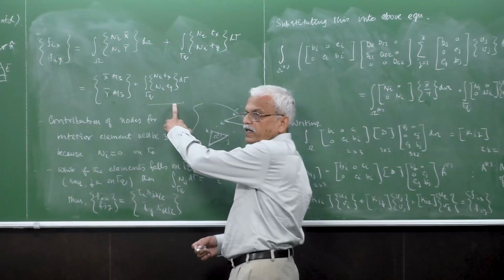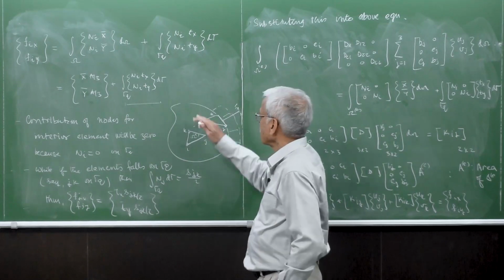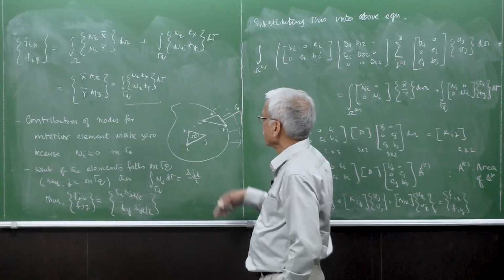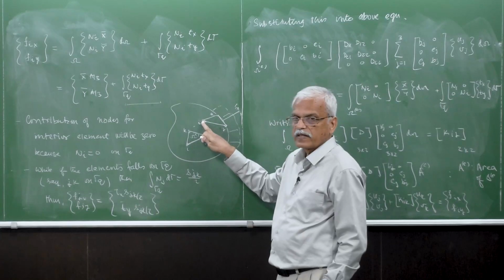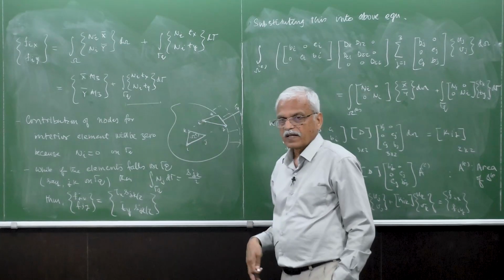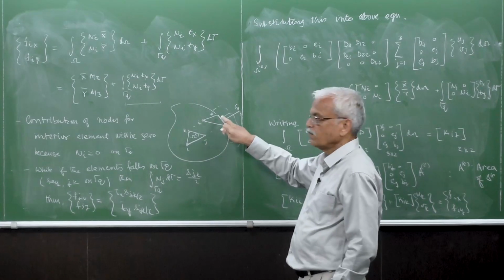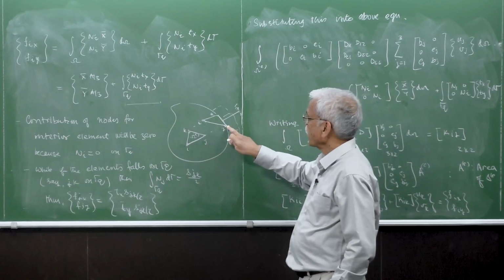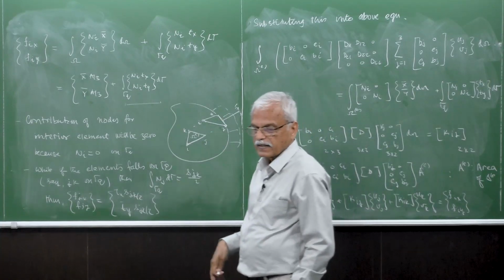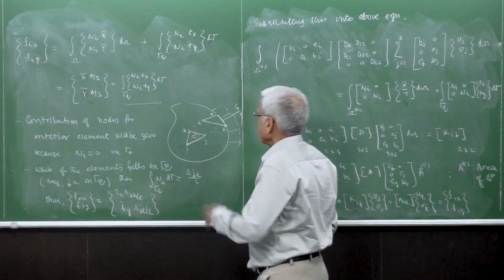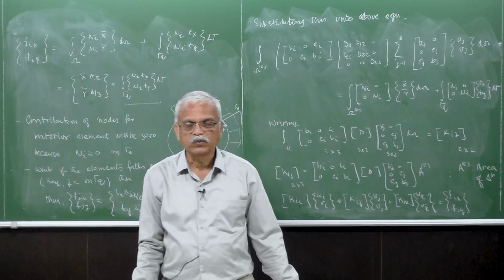So this contribution only comes into the picture for the elements which are there on the traction boundary condition. So even for this element, this node is interior, away from the boundary. So its contribution will be 0, 0, 0. Whereas for node J, if it has to be integrated along the traction boundary, that's along Jk for example, then its integral will be sjk by 2.